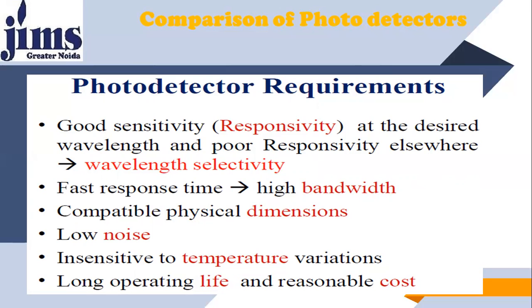So these are some points that should be in photodetectors, and we use photodetectors that fulfill these favorable conditions: good responsivity, wavelength selectivity, fast response time, high bandwidth, compatible dimensions, low noise, insensitive to temperature, and long operating life and reasonable cost.